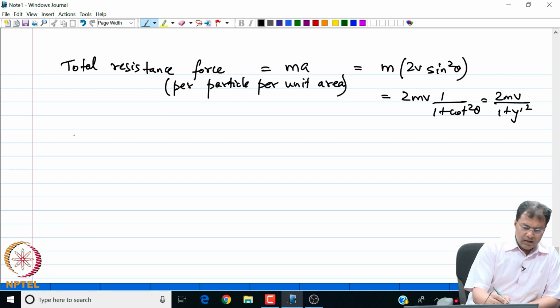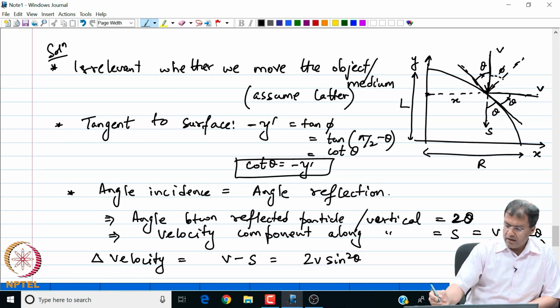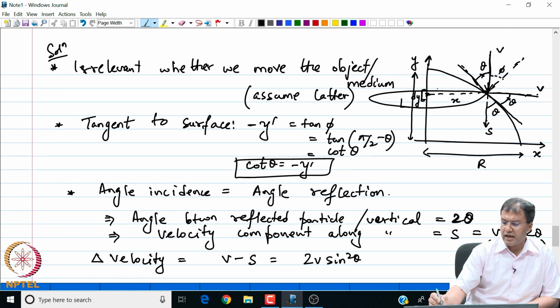Okay, so then notice again the figure, that we have a lateral surface area. So, we have to figure out the total force. The total force will be the force per unit area that we have just found, times the integration over the length. So, along one element dy, the perimeter, or the lateral surface area along the element dy, is 2 pi x.